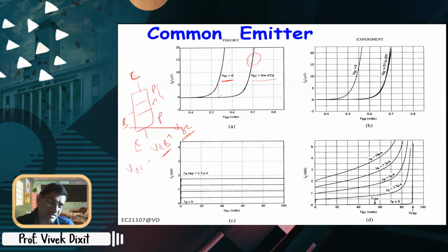So in that case, of course, your IB will be high because from both the sides the current will flow. And then if you reverse bias one of these, then current from the emitter will straightaway pass to the collector, and very small base current will be there.